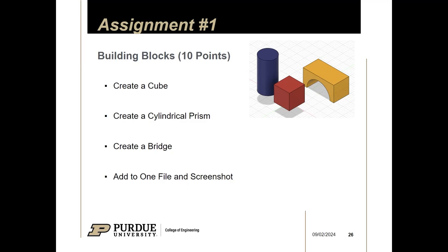For me, what I like to do, depending on the part, is I like to use the face. I like to start with the base that is most complex, because it might allow me to kind of combine operations to make the features or timeline a little bit more organized.